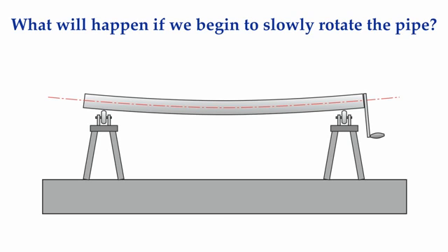The shape of the pipe as it elastically bends is called a catenary curve. It is very normal for a shaft to rotate on a curved center line of rotation. The amount of droop at the midspan between bearing points is typically very slight, especially for short distances between the bearings.